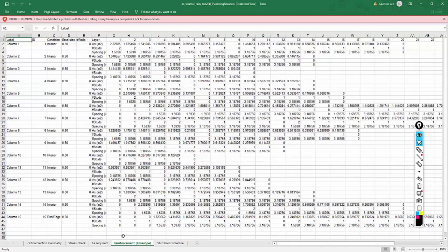If we look at reinforcement, that's also indicative here. We look at column 1, we can tell there's 0 reinforcement required at section 9, and then we build back up and we check those additional layers, and we have 1 additional stud for each one of those octagonal layers on each rail. So we get a need for more reinforcement because of this check.